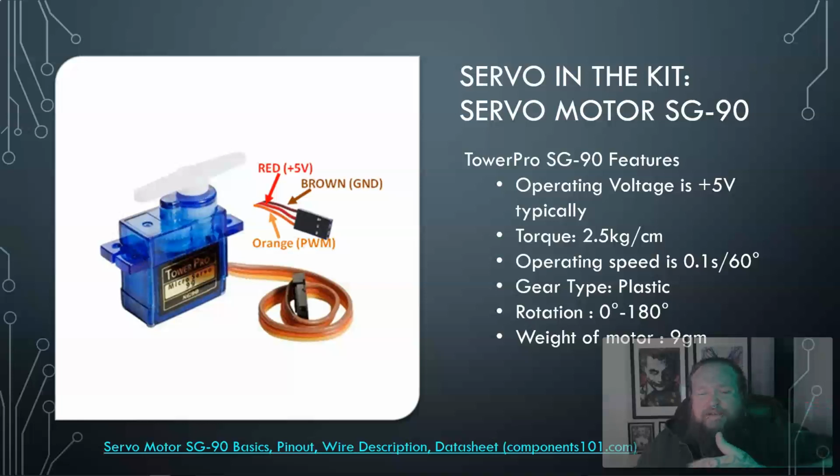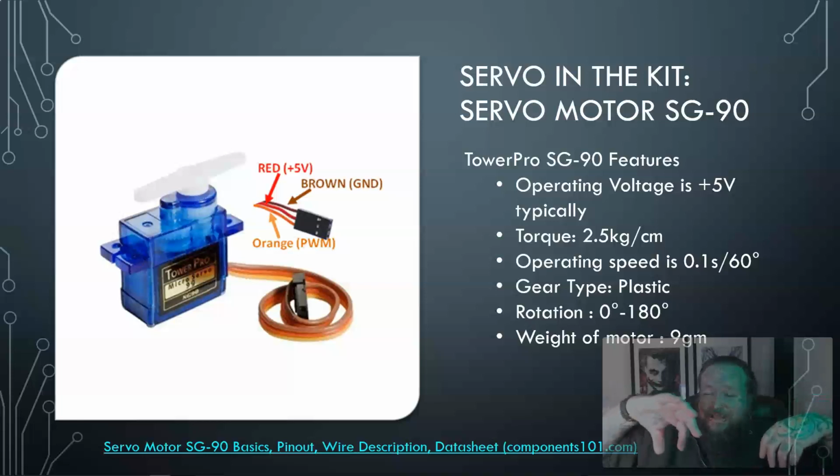So how fast can it go from 0 to 60 degrees in that time? Now 0.1 seconds seems fast for us, but that could be slower in motors and also with our code in between. And you remember, these are running asynchronously. So the idea is when you're telling it to move, your code is running, and then this thing is taking actual physical time to move, and your code could have gone past where it is, like basically it's running faster. And so two things are coordinating together.